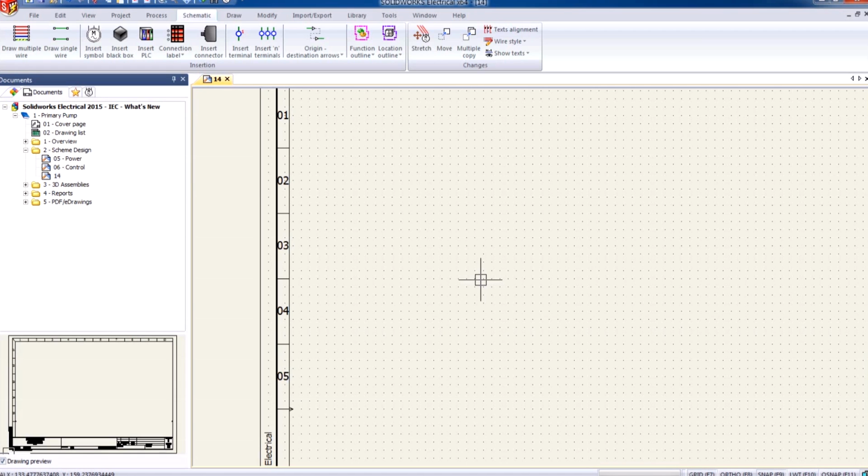We'll be looking at one of the newest features in SOLIDWORKS Electrical 2015, that is dynamic connectors. Until the 2015 release, if you had to show a scheme symbol for a large connector, for example a 24-pin connector, and at any given point during the scheme you only intend to use 6 out of those 24 pins, there was no easy or convenient way to represent that. However, with the 2015 release, this process has been streamlined a lot through the dynamic connector tool.